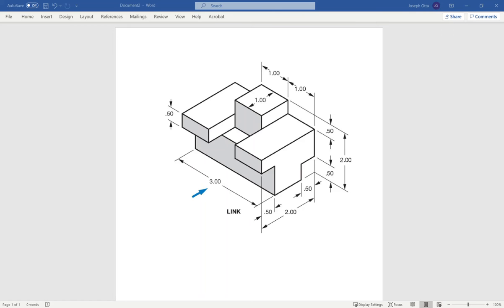Typically students ask, well, how do I choose the front view? Well, there isn't really a right answer to this. It's up to interpretation, but a good rule of thumb is usually the front view shows the major characteristics of the object. So the textbook uses the arrow to remove that decision making so we can focus on learning how to create third angle projection orthographic views.